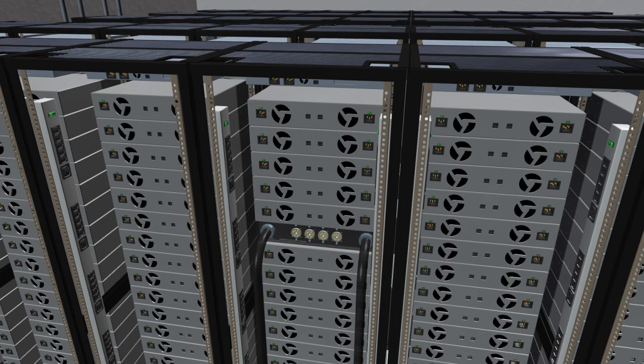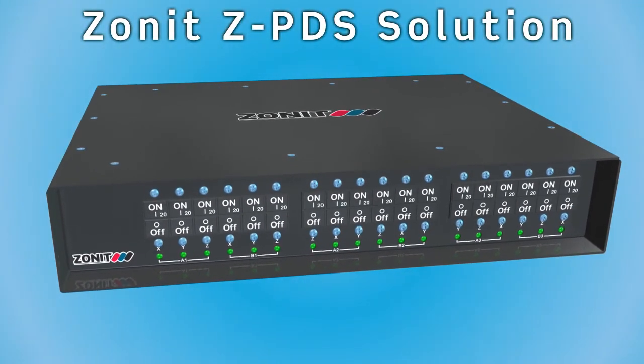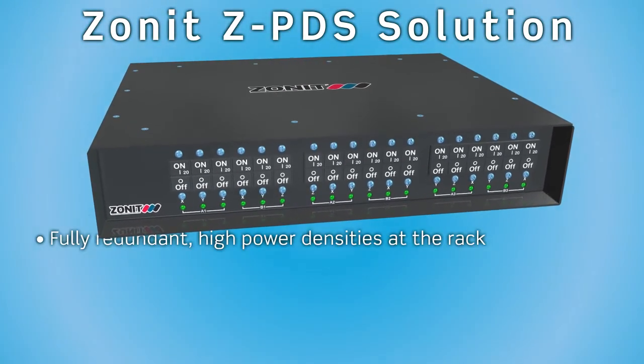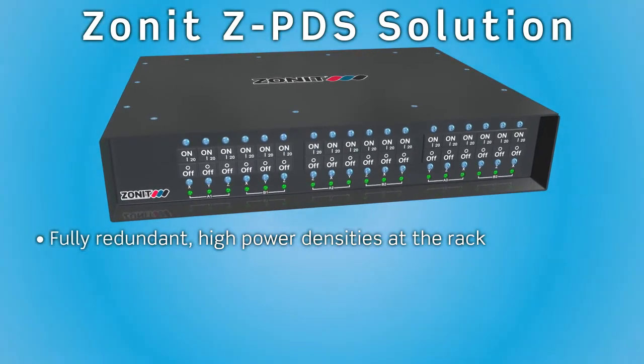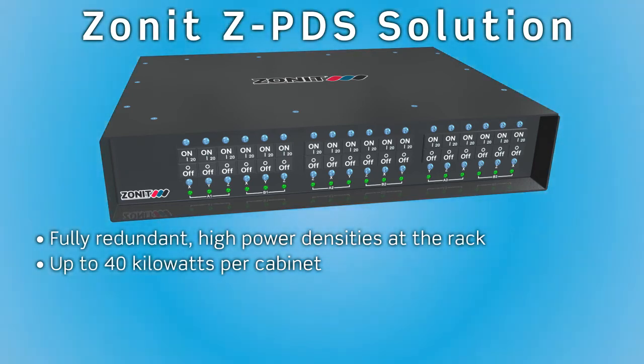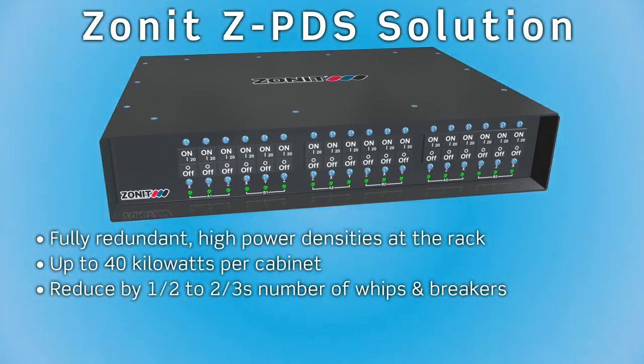In both methods, after deploying the Z-PDS, changes are made above the floor without interrupting power delivery. You can reposition the Z-PDS units as needed and handle the very few exceptions as they occur. In summary, the Zonit Z-PDS system gives the data center manager significant cost and operational advantages. It provides fully redundant, high power densities at the rack. The system will supply up to 40 kilowatts per cabinet. The Z-PDS system reduces by 1/2 to 2/3 the required number of power whips and breaker positions.